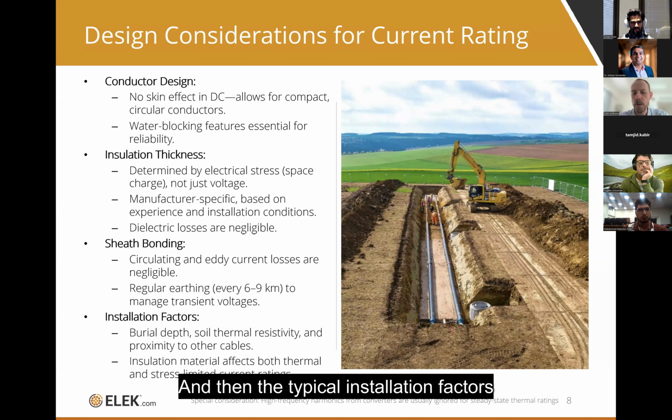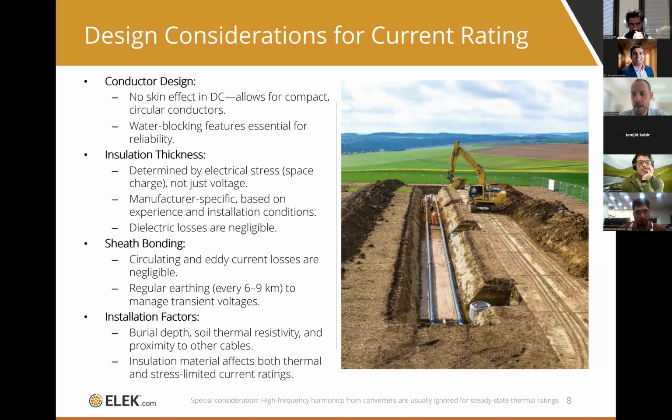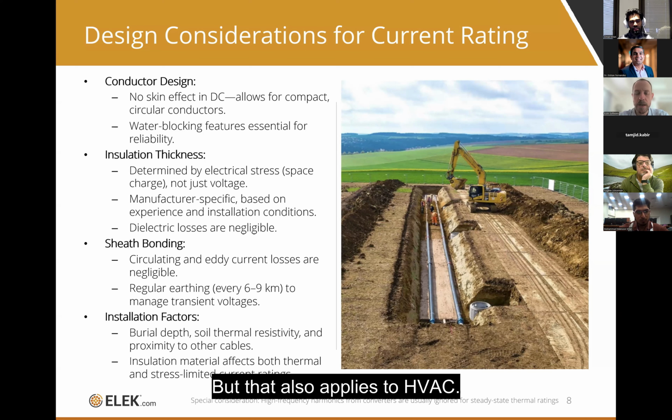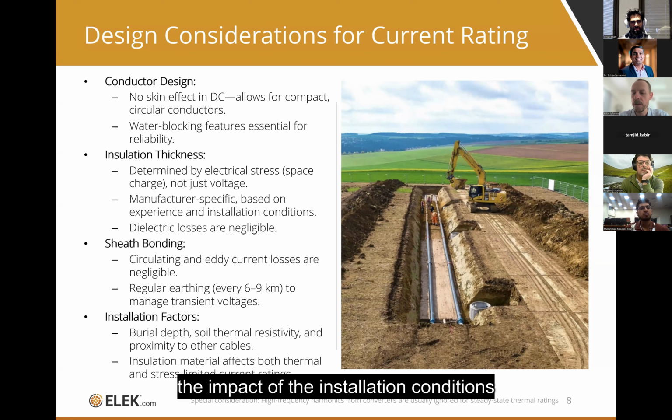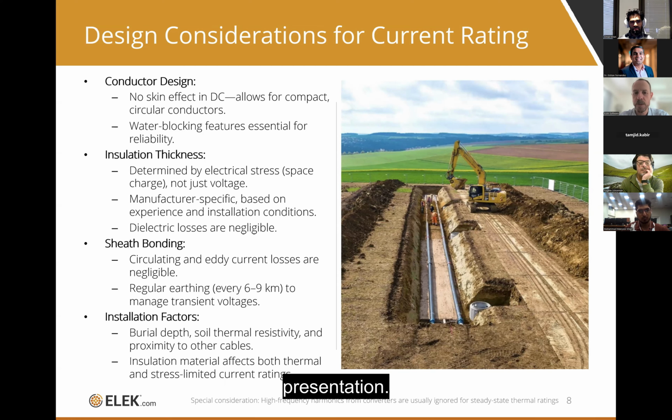And then the typical installation factors such as burial depth, soil thermal resistivity, and proximity or mutual heating between other cable circuits is also very important. But that also applies to HVAC. But you'll see the impact of the installation conditions on the electrical stress limits and the thermal limits for HVDC cables, which is very interesting and what we will be discussing quite a lot in this presentation.